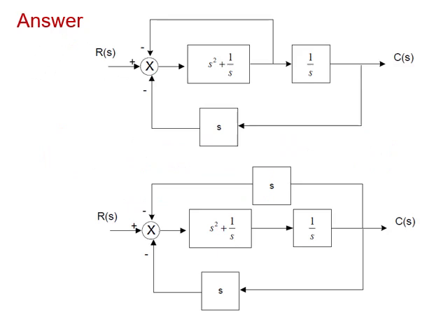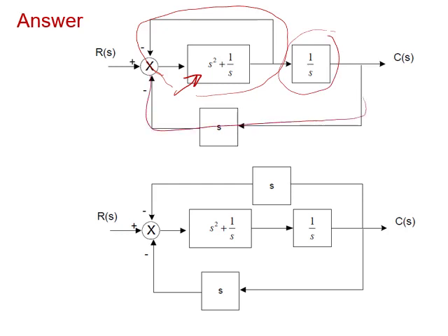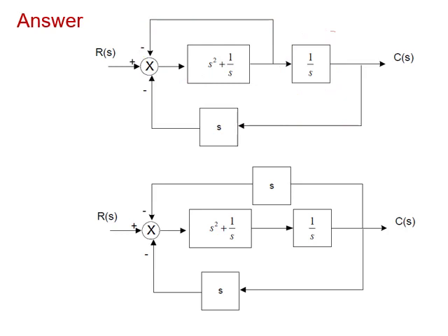So notice this is what I mentioned just now. This one, it's fine. Now notice that I have 1 over S here at this location. You have two choices here. You can consider this as a feedback and the result to be cascaded with 1 over S. The result will be fed back with this one. But then you are doing many feedback. Usually feedback has a high chance for error. That's why we don't do it that much unless we have no choice.